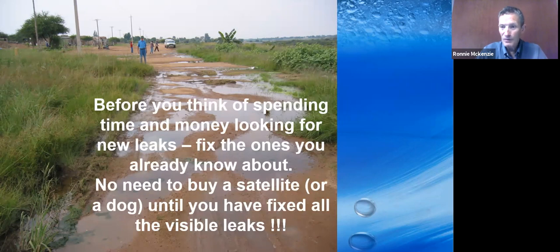So one of my takeaway points today is before you implement active leakage control, the most important thing is to fix the reported leaks that you already know about. If you're not doing that, I don't know how much point there is looking for new ones. Are you just going to make a list of all your leaks and not do anything about it? So rather use the money, fix the ones you know about.